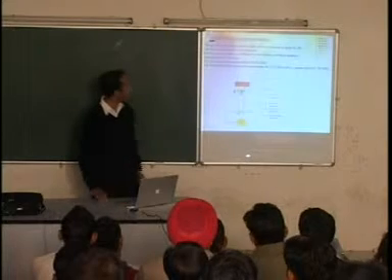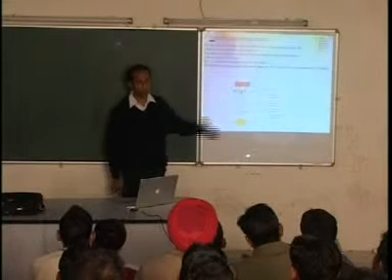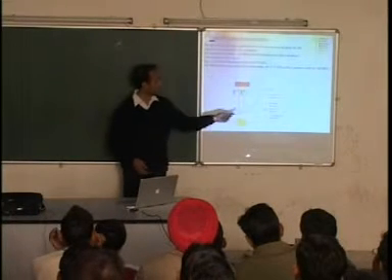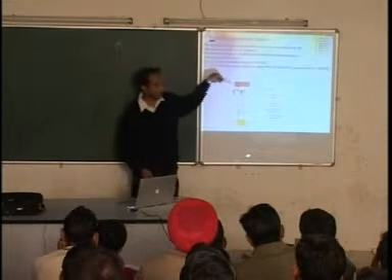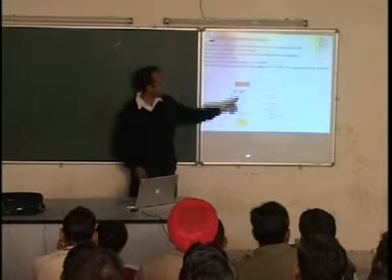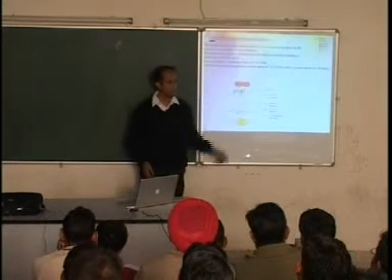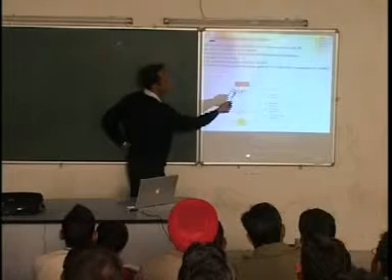Okay, so this is what I mean. These are the band stop filters. What band does it stop? Only the operational band. This is the bias circuit for the transistor. So the operational band, the 5 GHz signal, is not allowed to go in there. But what do I have here?